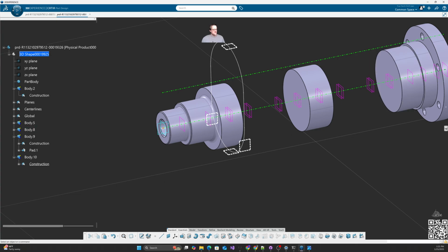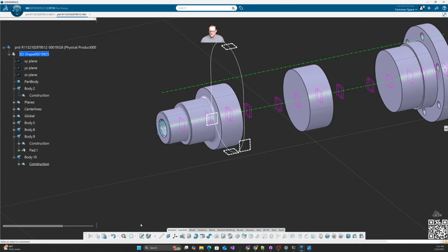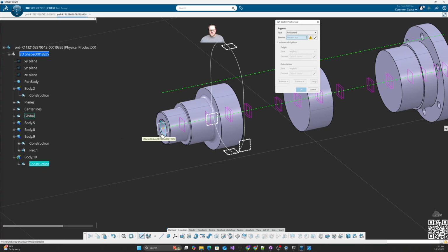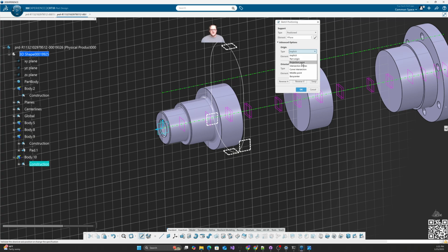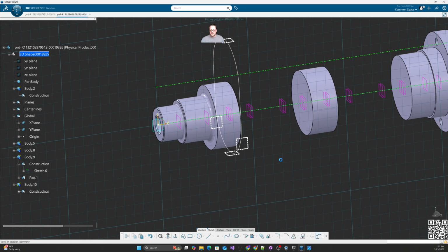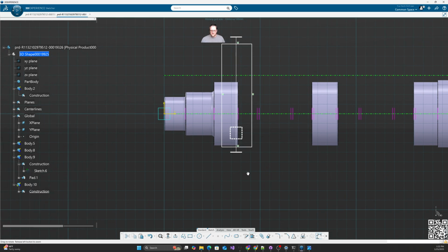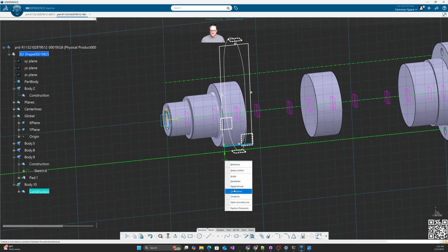What I'm going to do now is do the side profile. So in here, the dimensions are shown. So it's 25 from the top, which would be also 25 from the bottom, 5 in from the inner surface here, and that defines all of the geometry for that shape. So we're going to do that as well. So we're going to create a second sketch. So we're going to sketch on this plane, projection point of our origin, parallel to the line. And I'm going to start off just by drawing a rectangle. And we can then use these planes to define coincidences.